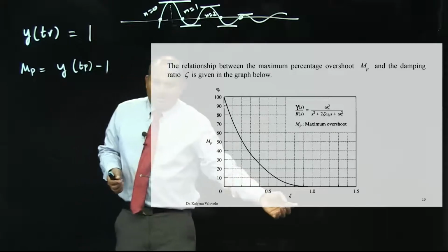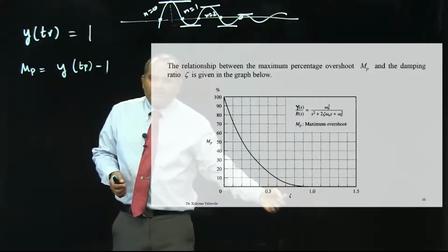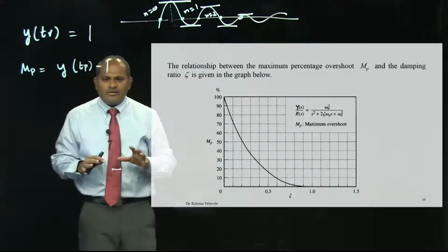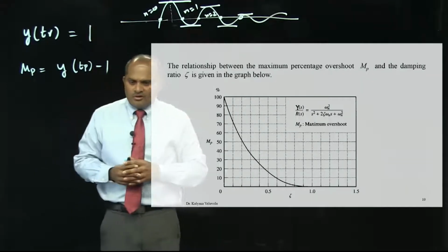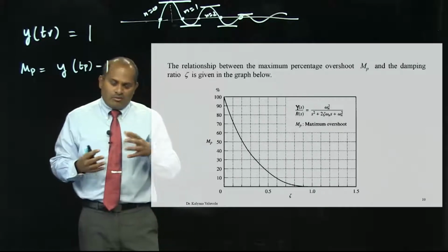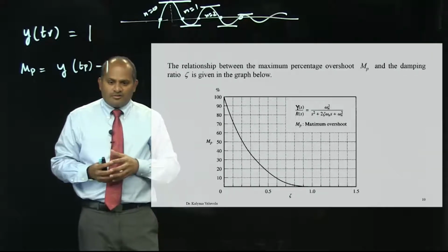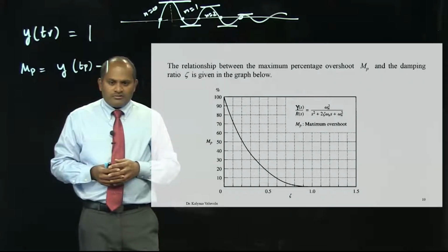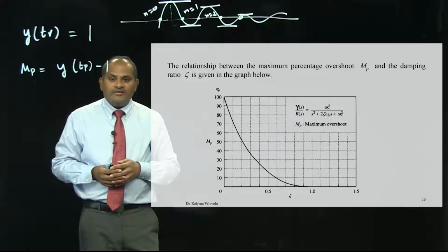So that is what I am saying, the actual damping is in this region, where acceptable limits of overshoot are generally between 5% to 10%. Good applications say 2%, 3%, but normal applications may say 5% overshoot. Many applications don't want higher overshoot. A good example is an elevator.